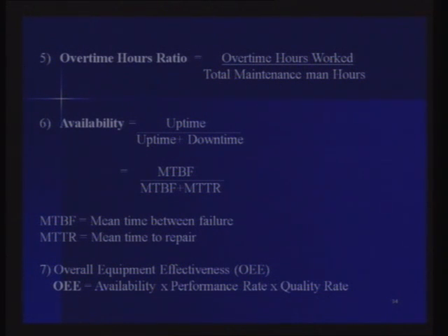That means how much time it will take to repair in case of failure. That is the downtime. So uptime is equivalent to MTBF and downtime is equivalent to MTTR. So ultimately the availability equation is MTBF divided by MTBF plus MTTR. So availability should be as high as possible.